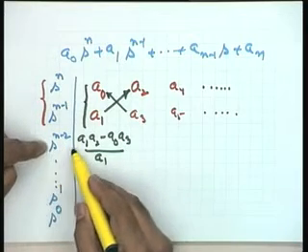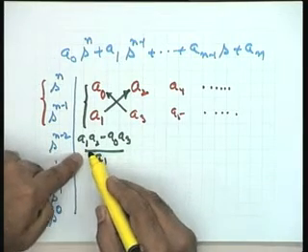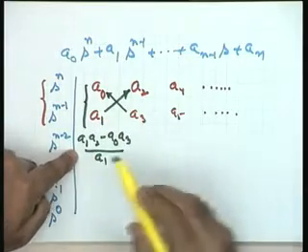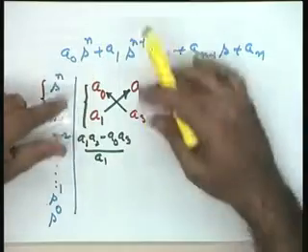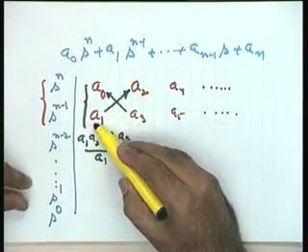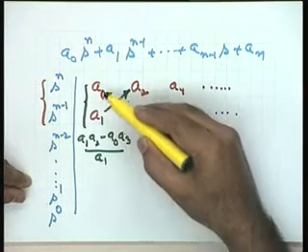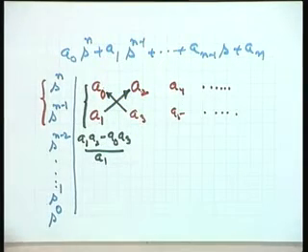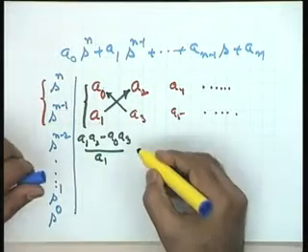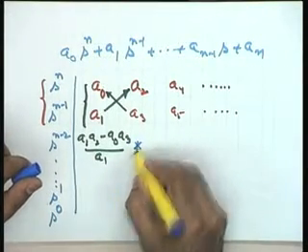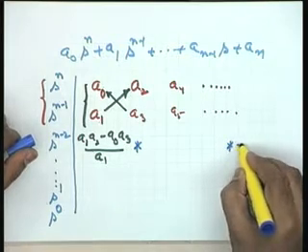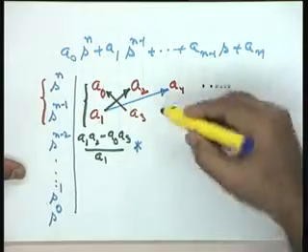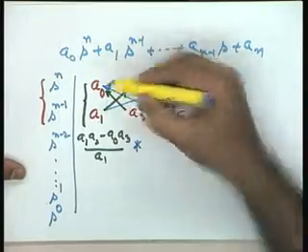So, the s n minus 2th row is under consideration. The first element of the s n minus 2th row is coming, and that element, I repeat now, is constructed like this. You take this pair and this pair, cross multiply, starting with a1 into a2 minus a naught into a3 divided by a1 is the first element. Let us look at the second element of this. Since the space is not there, let me put a star here and write star separately. Star equals what? Star will be equal to a1 into a4 minus a5 into a naught divided by a1.